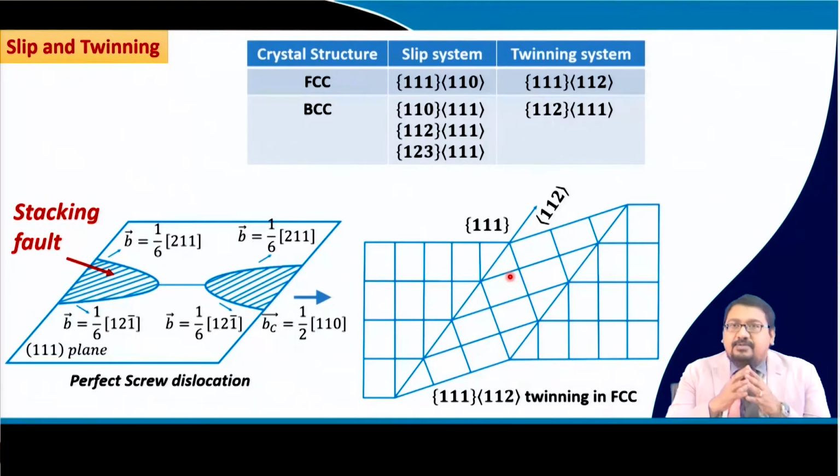Now, the hexagonal close packed materials also have multiple slip systems like the basal slip, the prismatic slip, and the pyramidal slip system, but it has various C by A ratios, right. So, depending upon the C by A ratio, the activities of various slip systems will vary, and under certain conditions contraction type twinnings or extension type twinnings occur, which I will explain in the later lectures.